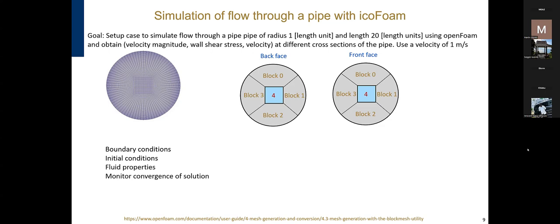If you have maybe 100 cells, the cell at the end, cell 100, should be equal to the velocity of cell 99. So we can set a zero gradient because the derivative at that point should be equal to 0, and you'll be able to calculate any value that you have. Now you set those conditions. So now we have the conditions for the velocity.